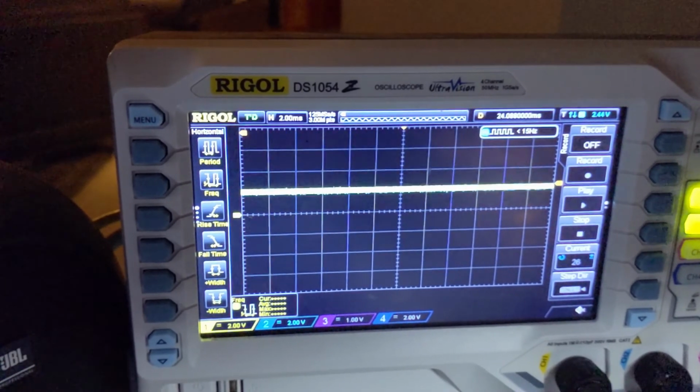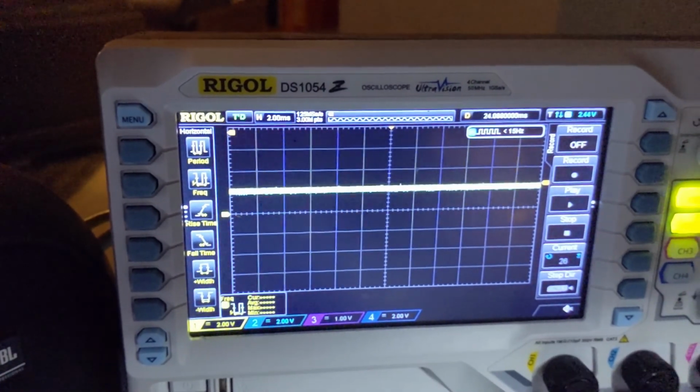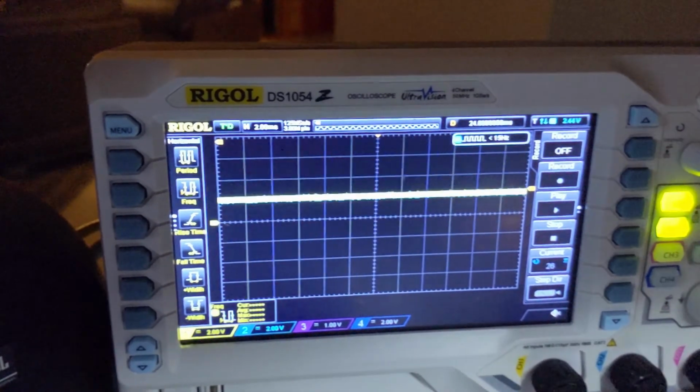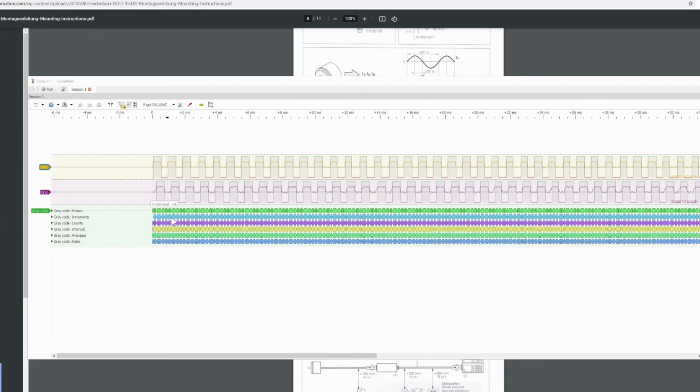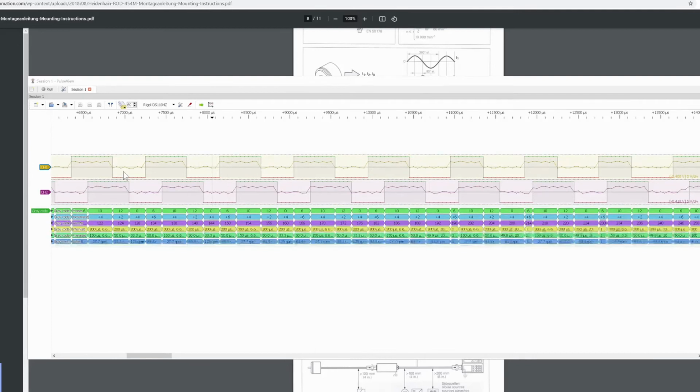And what I'll do next is I'll show you the view in Pulseview, which is kind of interesting. It gives a little more detail. So here is the view from the oscilloscope into this application called Pulseview, which is a logic analyzer. And if we zoom in, what you're going to see is for each channel, channel 1 and channel 2, what we just saw is the yellow one and the blue one. The little squiggly line here is the analog signal, and then this square wave here is like a virtual Schmidt trigger processed logic signal.